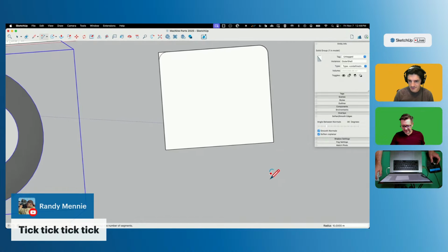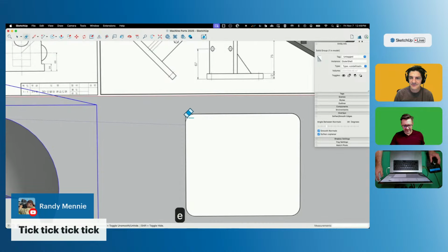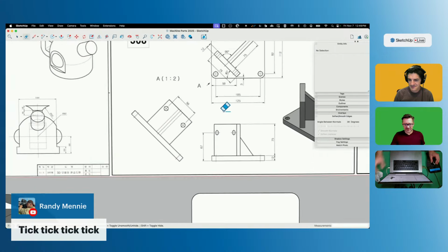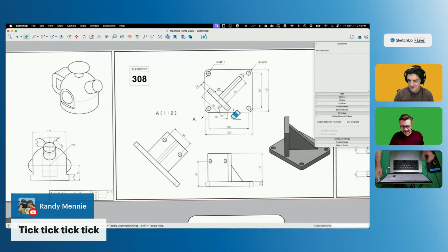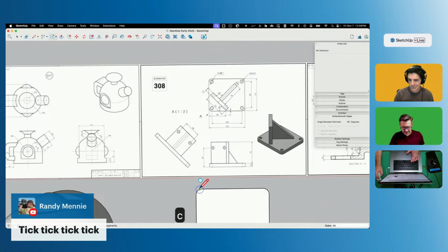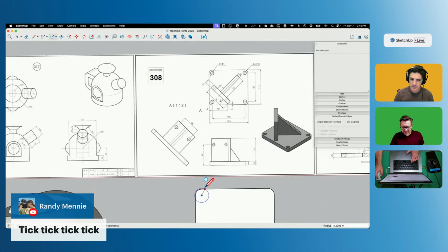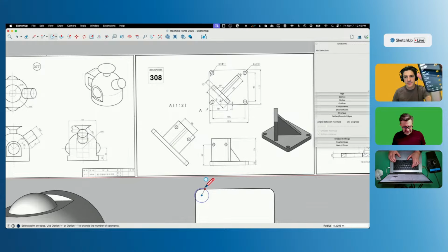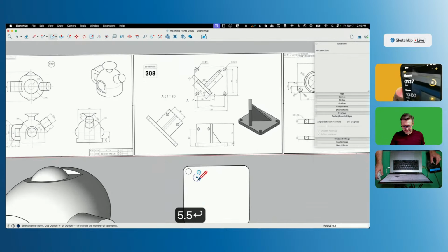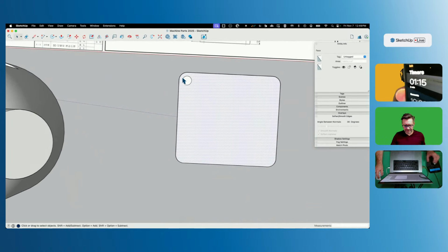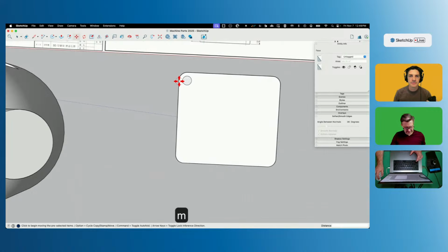All right, I'm gonna double click. I'm gonna get rid of my circles first, which should line up the same spot. So I should be able to say circle, inference off of this there, and then that is 11. So that's 5.5. All right, and then I'll take that, inference that down here. Take both of these, inference that across from here.